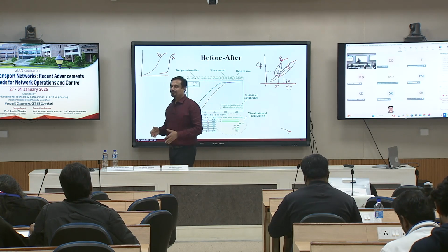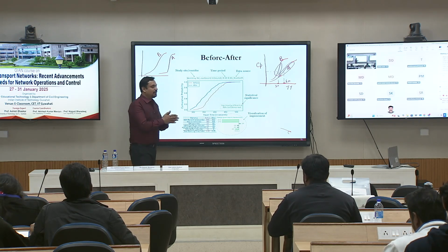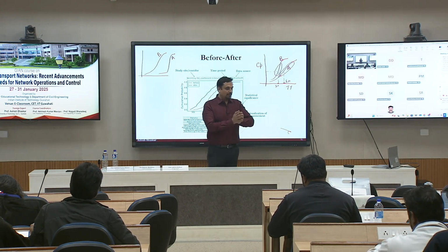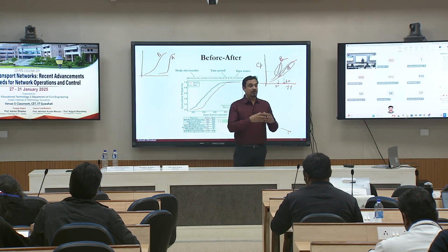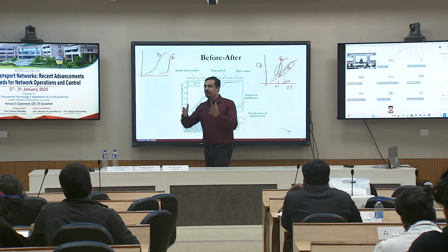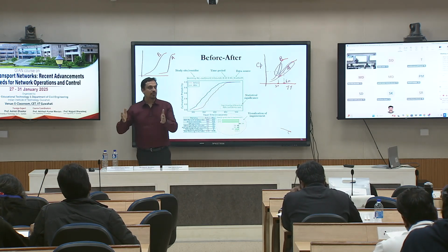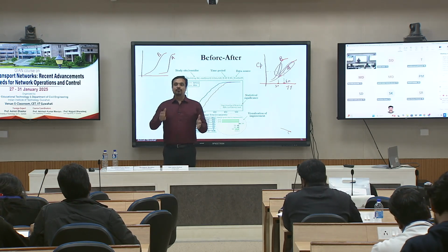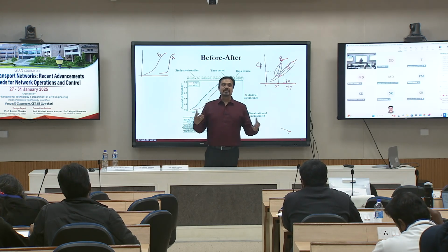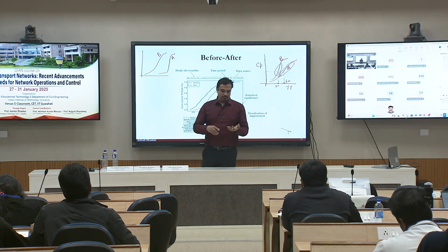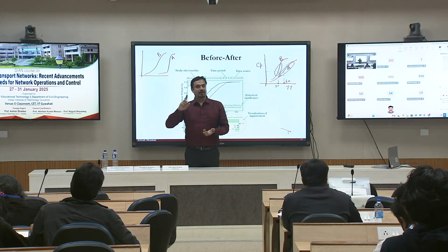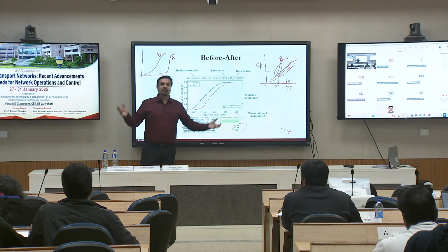Second was, I've shown you that the process to optimize the signal time or to retime signal timings is very tedious work. You have to define the time periods for which you have to adjust the signals. You have to define the demand and the optimization to be done. You have so many data sets. We have discussed, at least in Australian conditions, Bluetooth, loops, trajectories that are available to you.